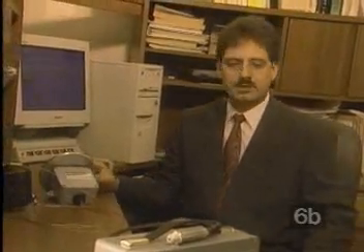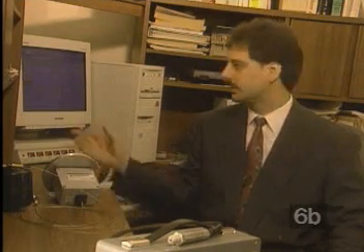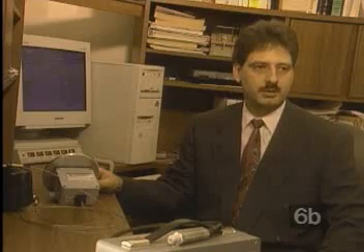We take the sensors into the lab, and since we have known parameters such as water freezes at 0 degrees centigrade and water boils at 100 degrees centigrade, we can take our temperature probe and put it at these temperatures, plus other known temperatures by using lab equipment, and gather enough data so that we can take them back and enter into the computer the different voltage levels that we've gathered, and calculate the coefficients for our fifth-order polynomial.